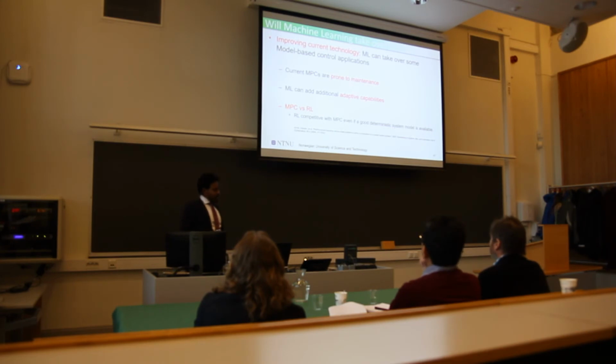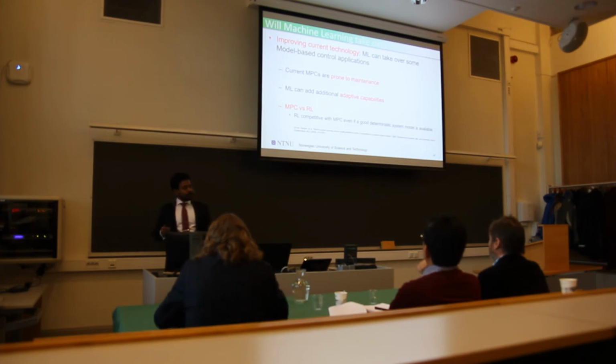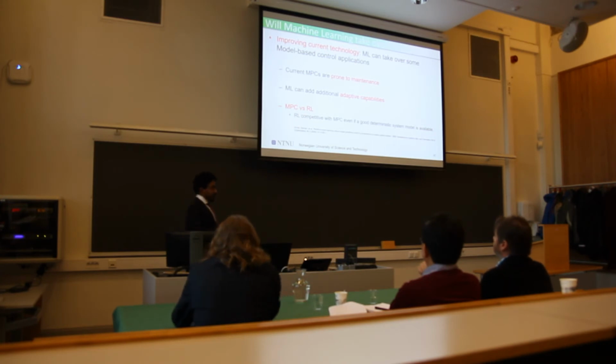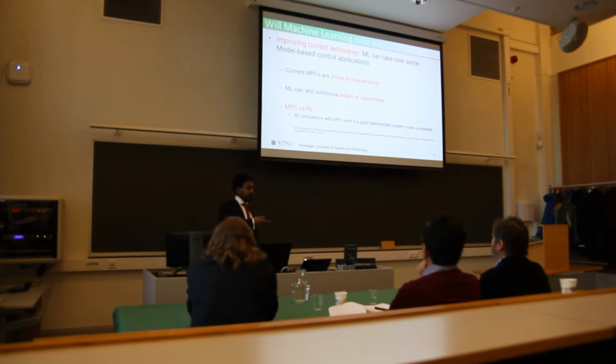So, machine learning can definitely improve the current technology, can take over some of the model-based control applications like MPCs, as I talked about. It's linear MPCs that are often used in industry, and they are prone to maintenance because you have to relearn your system or re-identify your system after some time because some disturbances or some changes in the process have changed it, which is always the problem with maintaining MPCs, where machine learning can add some adaptive capabilities.